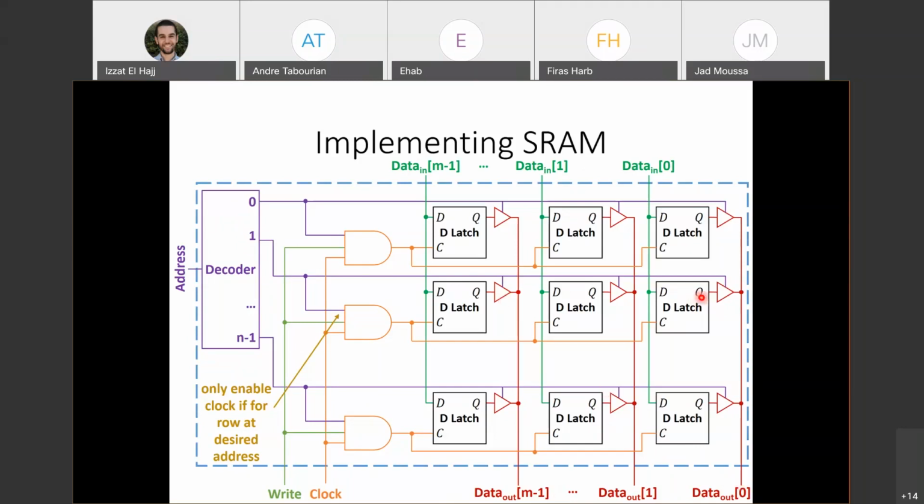And when we're reading, say we pass an address to read, write is always set to 0, right? So that signal will never come out of the AND gate at the same time as we're reading. Yes, correct. So here, if write is set to 0, that means we are reading. If write is set to 1, that means we are writing. Okay, so because it can never be both 0 and 1 at the same time, they're exclusive.